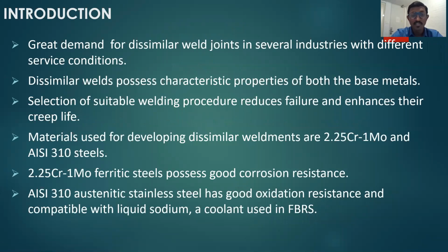Dissimilar weld joints are gaining wide acceptance in several industries nowadays due to their unique characteristic properties to withstand the different service conditions in these industries. The dissimilar weld joints possess the characteristic properties of the base metals from which they are produced. Besides this, a suitable welding procedure adopted for joining these dissimilar steels can enhance the creep rupture properties of these weld joints.